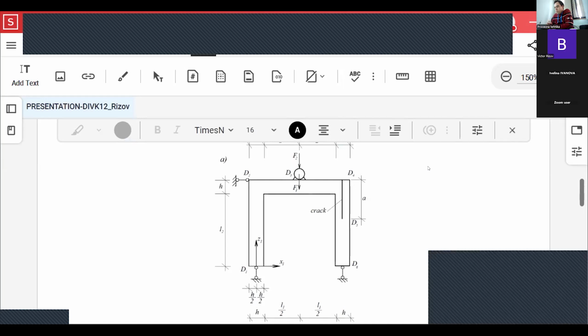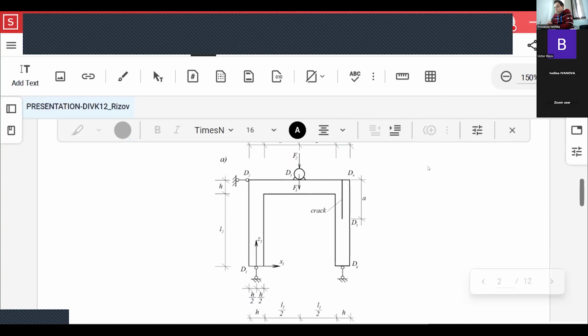Frames with three types of supporting conditions, namely 3 links, 2 links and a pinned support, and 2 links and a fixed support, are explored here. The principal aim is to evaluate the influence of the supporting conditions on longitudinal fracture in frames when the latter are acted upon by periodic dynamic loading induced by a motor installed on the horizontal member of frames.